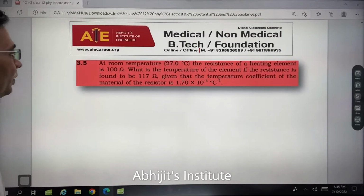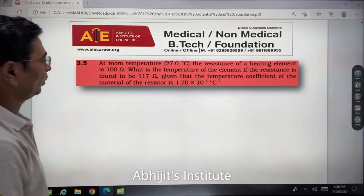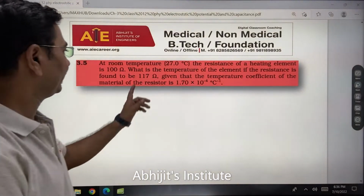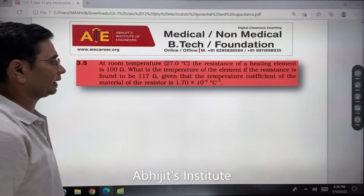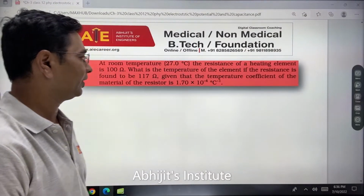So at room temperature 27 degrees, the resistance of the heating element is 100 ohms. Okay. What is the temperature of the element if the resistance is found to be 117? Okay, 117 हो गई है, 100 से लेके 117 हो गई है. Given that the temperature coefficient of the material resistance, that is this. Okay, alpha is given to you.